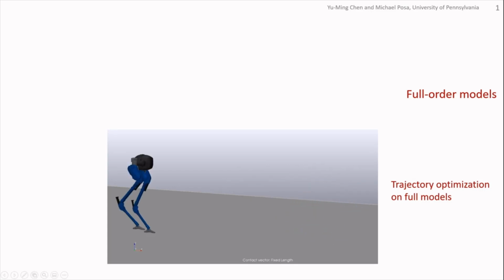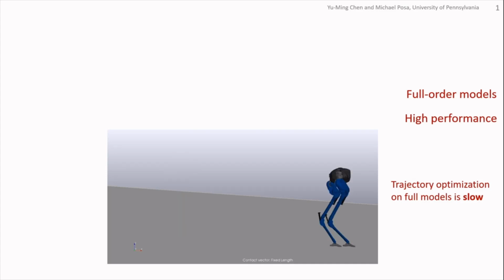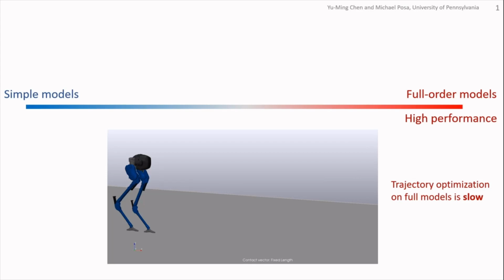In the optimization, we use a forward model which can describe the motion of the links of the robot, so this approach could leverage our full knowledge about the robot and generate an optimal trajectory for each joint. However, this method could take up to a minute to plan for just a single footstep. Therefore, some people use simple models such as the linear inverted pendulum.